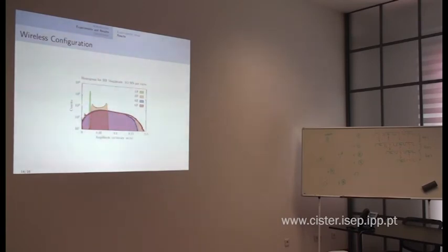When it goes here, it will de-amplify. And with that, if you have enough dynamic range, and your amplifier can change fast enough, then you can always be adjusting and you will never have a signal that is too weak or too strong. However, when you amplify and you come to this quarter here, if you do have noise, you can amplify as much as you want, but you will also amplify the noise. So the signal to noise ratio cannot be altered by amplifying, and that is still a problem.